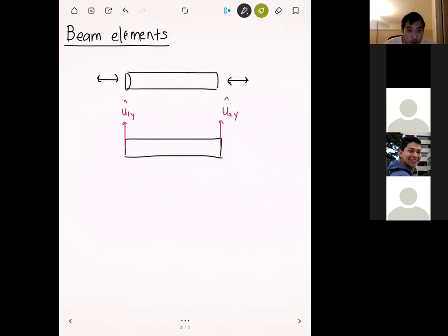And then in addition to this, we can also consider rotations. That's basically to denote how an element can be twisted and change its orientation. You can think of cases where maybe the left end of the beam right here is not moving, but it's twisted in a certain way based on how it's loaded. These are two modes of deformation that we haven't considered yet, because they're not part of the truss equations. An element that can support these two deformations is known as a beam.